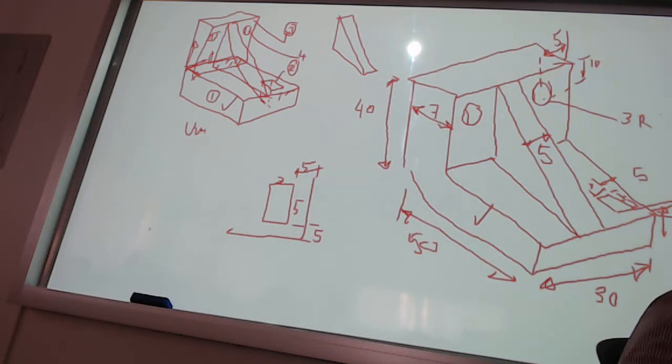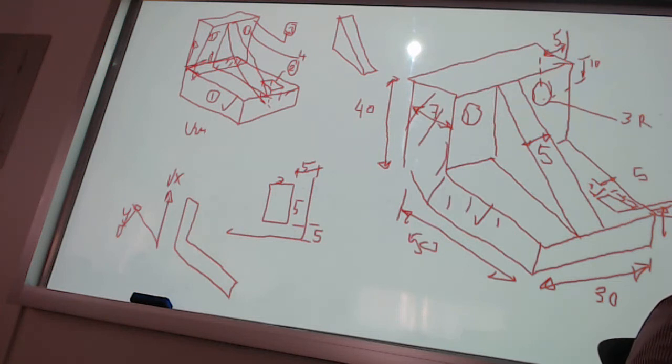Let me tell you the story. I myself, if I'm thinking about this problem, may think about it in a different way. What is a different way? I can make our XY vertical. This is our XY plane. Okay? And just draw that shape. See, this is your XY plane, and what I'm doing is just drawing that side of that object. And then after drawing that part, I'm going to make press pull or extrude to come up with the whole angle at once.